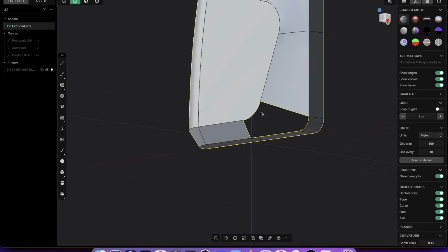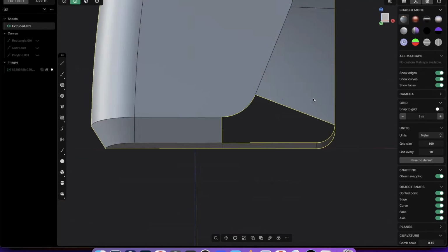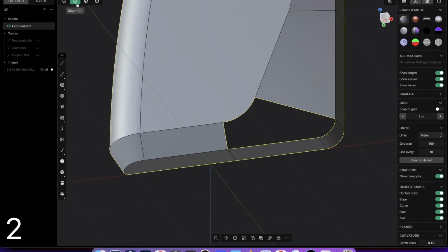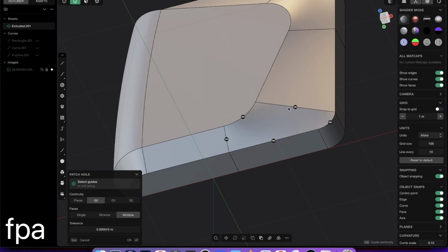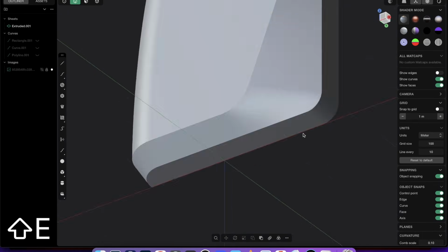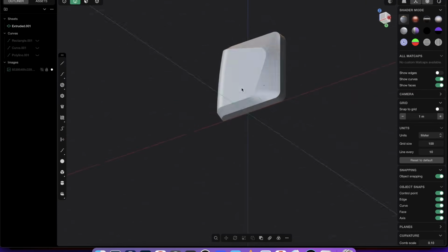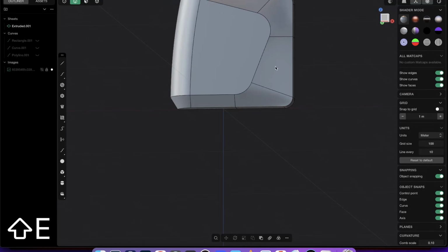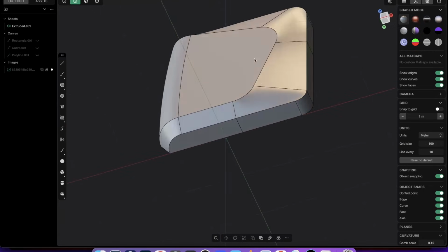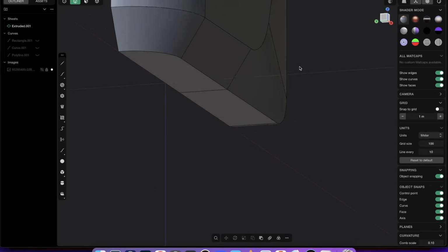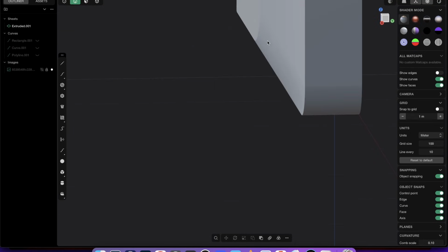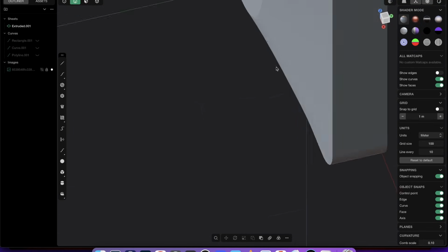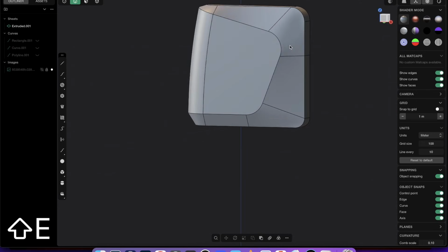Let me come back to that in a second. So let's first close this guy here. So also press 2 and select this whole loop and again patch it. And select here G1 and here G1. And just look how it looks. And we basically have the same situation. So here you see it's very, very curved. So you see this does not really work.